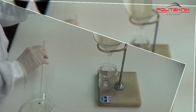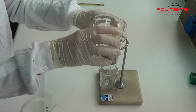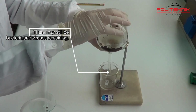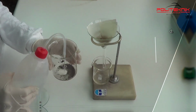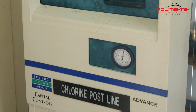Once the water has gone through the filtration process, it is about as clear and clean as it can get. However, there may still be bacteria and viruses remaining. To ensure these are destroyed, there must be a disinfection process employed. The most common disinfection process used is chlorination.